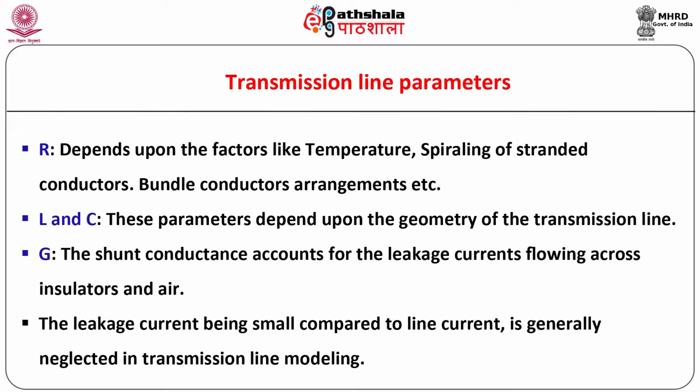The breakdown strength of the dielectric medium limits the voltage of the transmitted signal, which in turn limits the power carried by the transmission line. It should be noted that this property is independent of the frequency of the signal. How much is the breakdown strength? For air, the breakdown strength is a few million volts per meter.